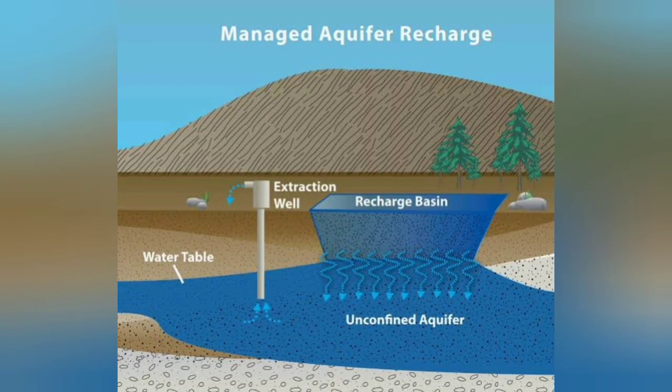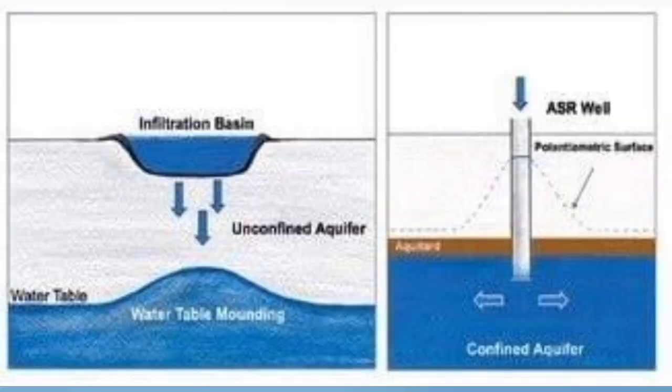Now, the next requirement is source water availability. As we have discussed, this is the first requirement. You should have some water, then only can you recharge any pit or anything artificially. The availability of source water is one of the prime requisites for groundwater recharge and is basically assessed in terms of non-committed surplus monsoon runoff, which as per the present water resource development scenario is being unutilized.